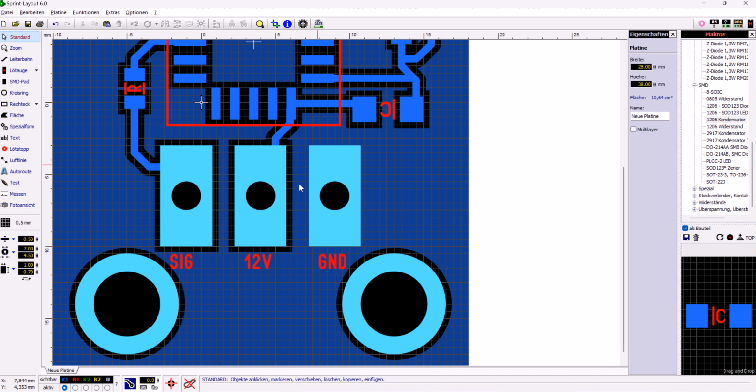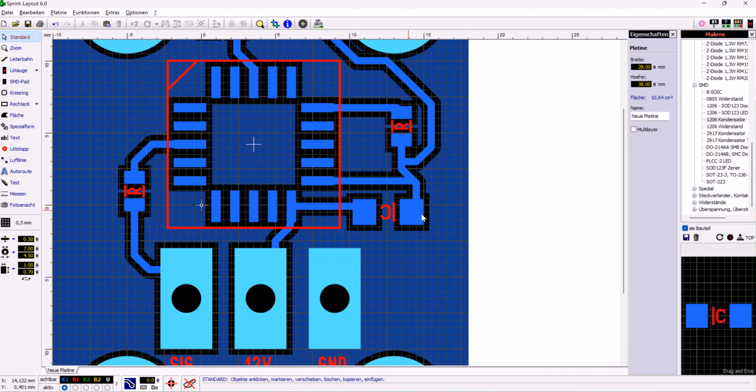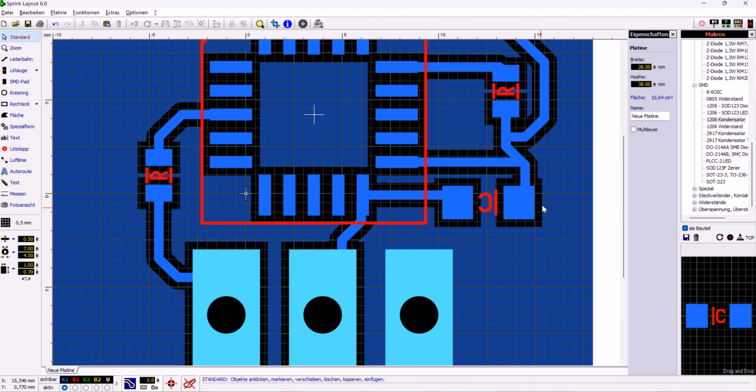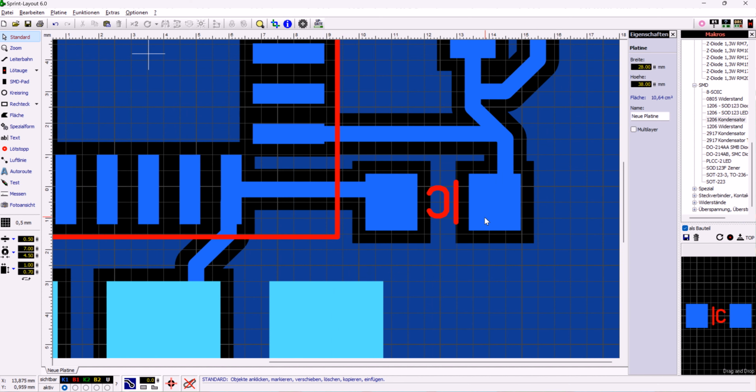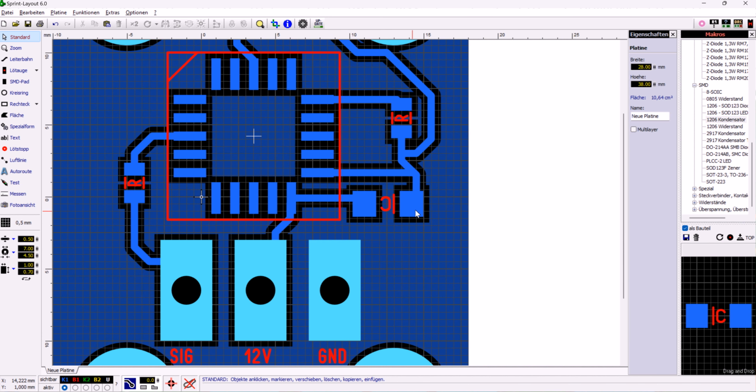In some cases like here, that would be a wire which you would hand solder mostly. It should not be a problem, so we could leave it at that. But on SMD components, you of course don't want to put your soldering iron on there for too long, or if you are soldering with solder paste and hot air reflow the PCB, there can be problems with so-called tombstoning.